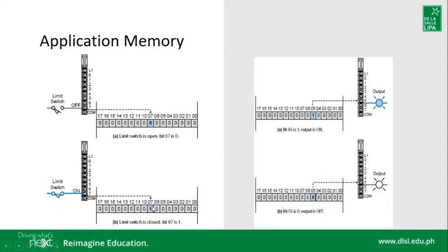It only goes to show that also in the output, if in the program the output is being triggered at address 05 and it's been triggered as the output is equal to 1, it will send the signal going to the output terminal at address 05, making the lamp turn on.